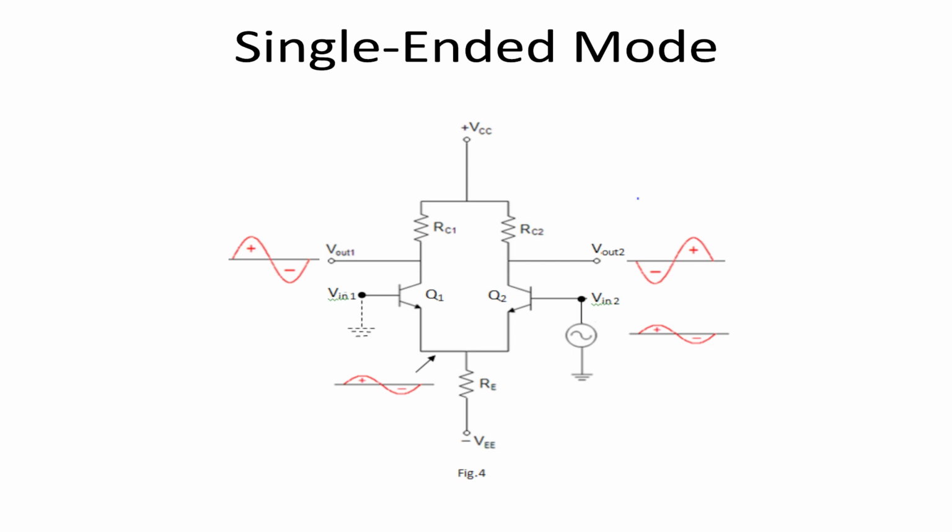That is the first look at applying the input, and this is called the differential mode of the amplifier. This is V1, this is V2, so this is minus and plus. We know that our output is equal to, in this case we are assuming the negative terminal is given V1 and the positive terminal is given V2, so V2 minus V1.